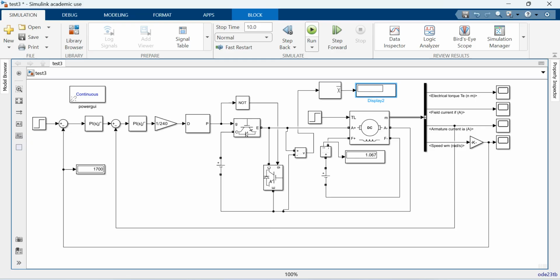So now again if I run, yeah, initially the voltage is around 180 volts, which is fed 170. Let me settle. Once it is settled, it will also settle. So at 1500 RPM, around 160 volts is given to the armature, which is varied via the DC chopper.